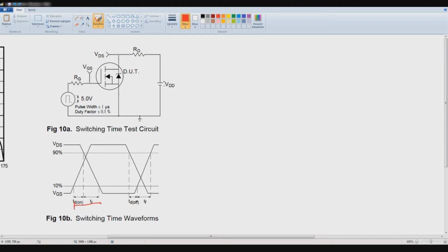So this part over here is then, you then get this overlap, which means switching losses, because as this goes down you get a current flow from here to here, and as the gate approaches max you have maximum current flow, as you saw in the graphs earlier, for example.